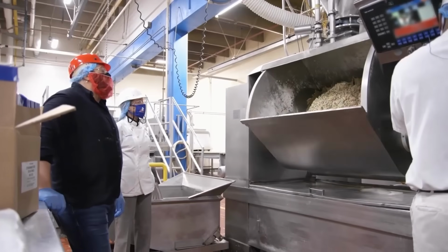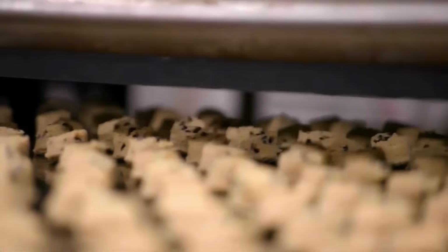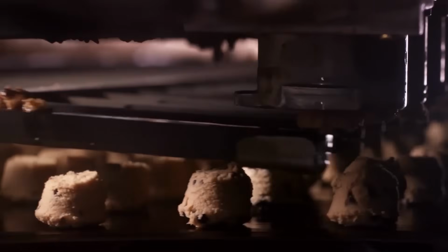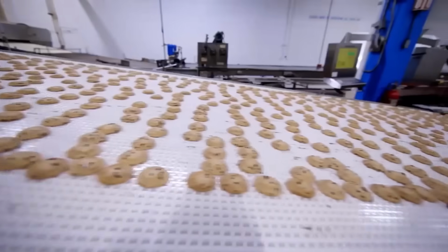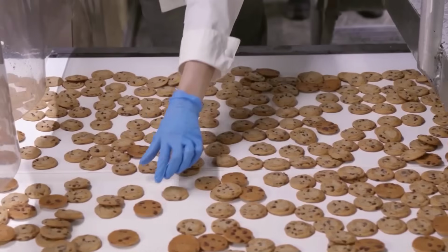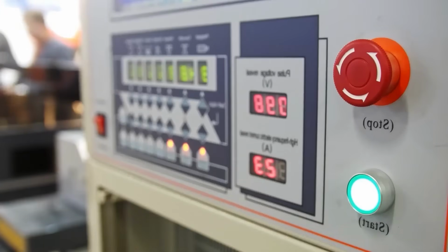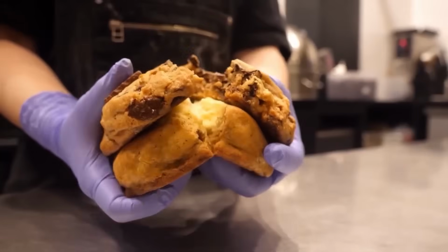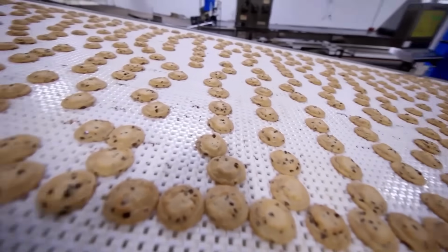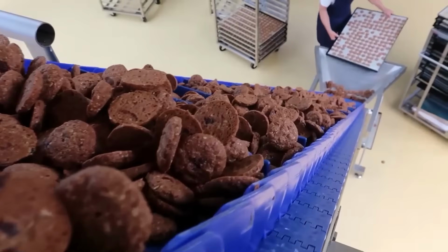The baking oven is a hybrid convection and radiant tunnel oven with multiple independently controlled heating zones. Total bake time is typically between 8 and 11 minutes. The oven band runs at a set speed that is continuously adjusted by a PID controller based on real-time surface temperature and humidity readings. Oven zone temperatures range from 160 degrees Celsius in early zones to up to 210 degrees Celsius in final zones to ensure progressive starch gelatinization, moisture evaporation, Maillard reaction, and fat migration.